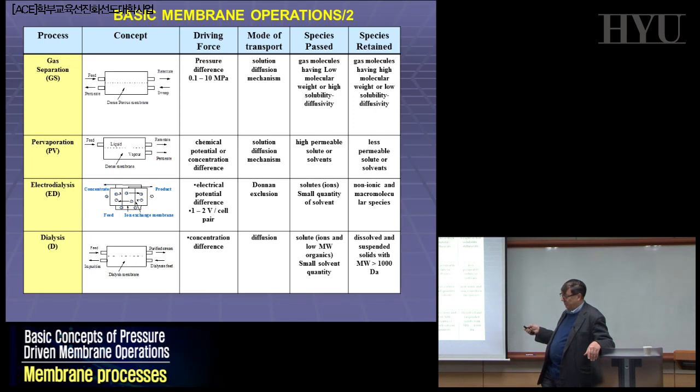Also here, we must have a polymer in which oxygen can be easily dissolved and nitrogen does not dissolve, or methane, or hydrogen, whatever it is. If you have a material with different levels of solubility for the different penetrants, you can realize a thin film and, applying an appropriate driving force, one of the species will be dissolved in the material and transferred to the other side. And that's what some of you are doing, studying materials with a high level of porosity to increase the flux without increasing too much the delta P.